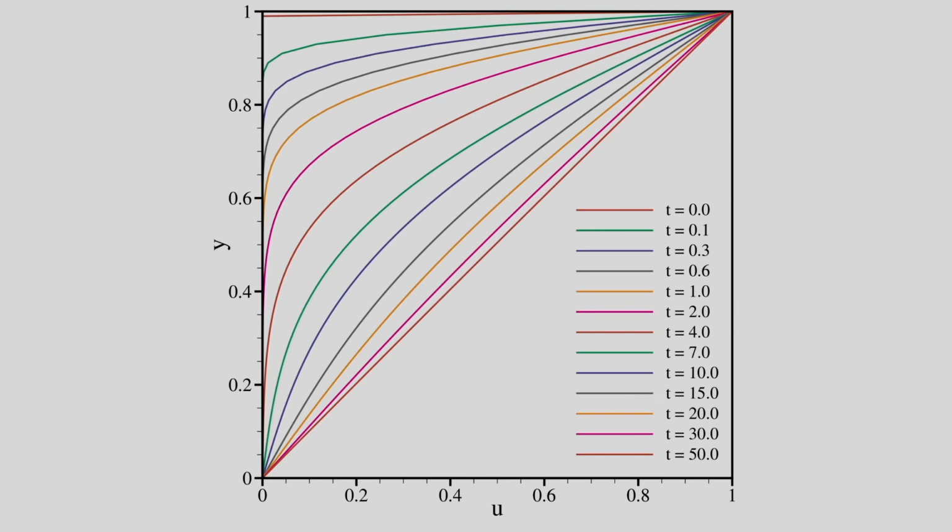So, you can see with different time instances. It is t equal to 0.1, okay, this is t equal to 0.3. As time progresses you can see inside this fluid domain the velocity is progressing. After that, at t tends to infinity, obviously it will be steady, because it is a steady state problem, but we are marching in a pseudo transient way.